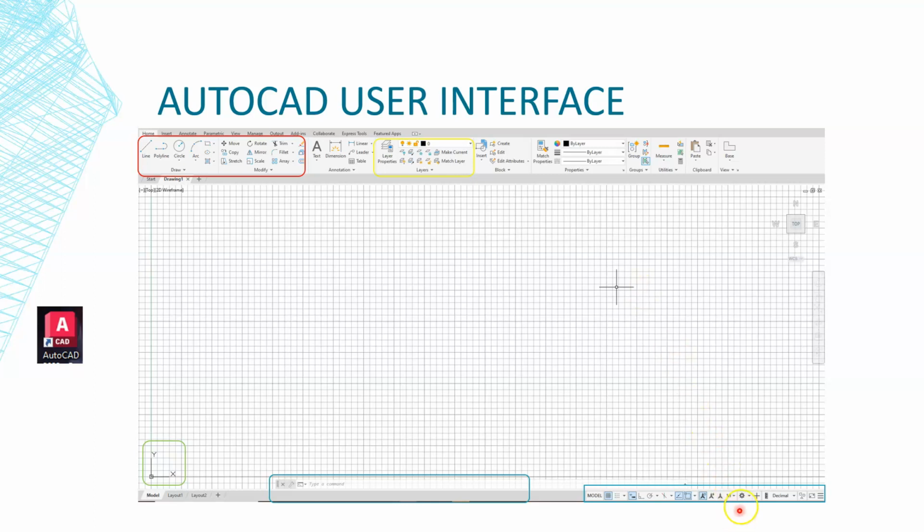The last thing we're going to take a look at here is this quick access panel. So when we're interacting with AutoCAD, especially with function keys and things of that nature, you're going to see these buttons light up. Now remember that anytime these light up as blue, that means that they are activated. For example, on this one, you can see that the grid is turned blue, and you can look in the graphics area here and see all the lines and things of that nature. Some of the things that we're not going to really get into is this view cube. This deals more or less with 3D stuff. So we're not going to have to worry about that.